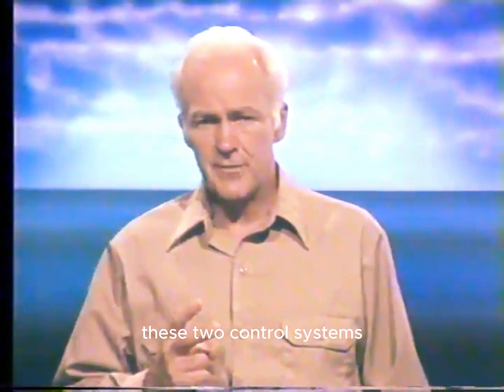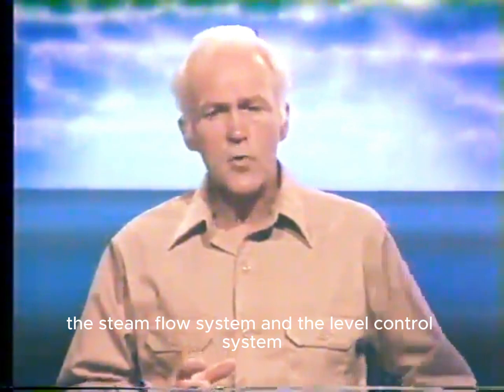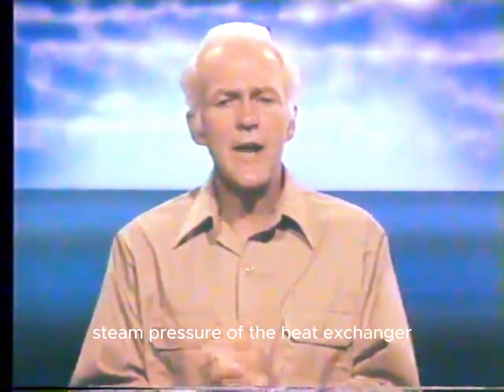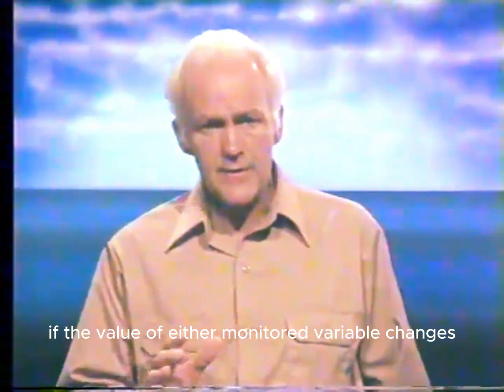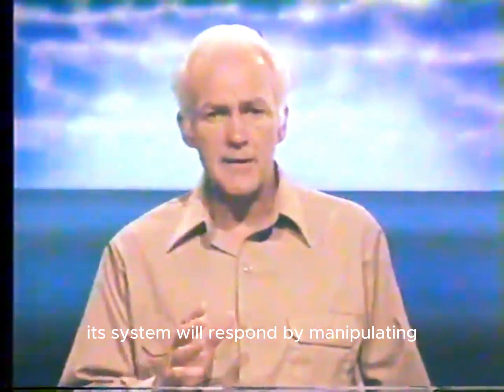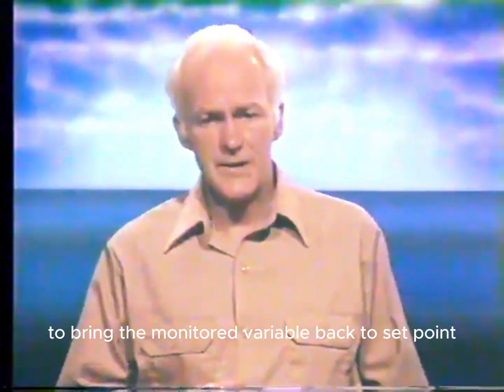These two control systems, the steam flow system and the level control system, work together to keep the output steam pressure of the heat exchanger at set point. There are two monitored variables, water level and steam pressure. If the value of either monitored variable changes, its system will respond by manipulating either steam flow or water flow to bring the monitored variable back to set point.